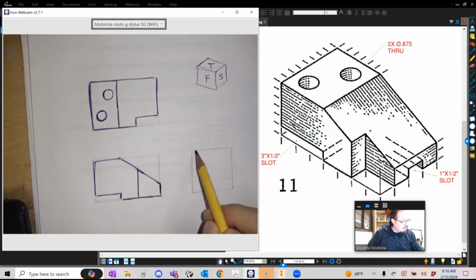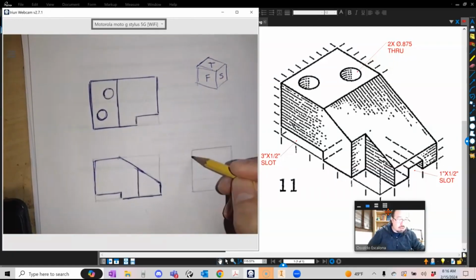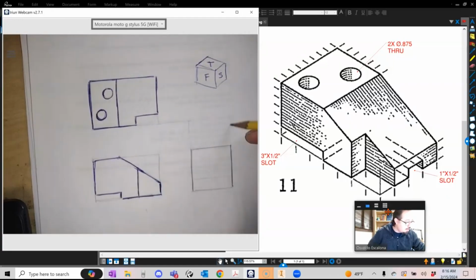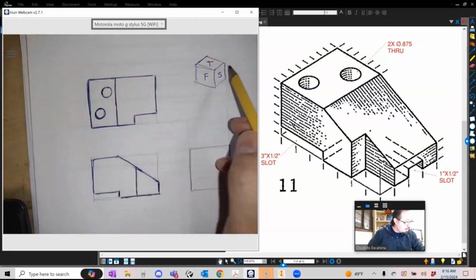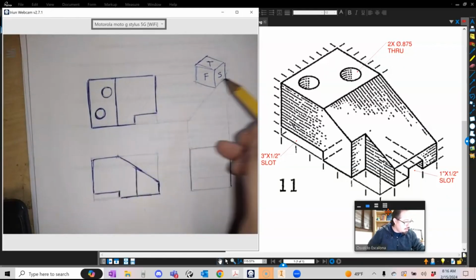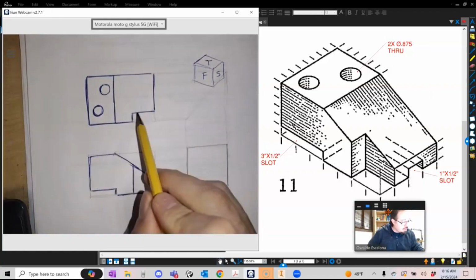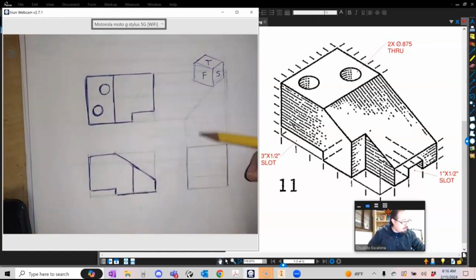So if I were to look at the side view, it seems to me it's going to go across the whole part, something like that. And then it seems to me here, I can make a little 45-degree line here. Because if you do a 45-degree line, you can actually get the right depth. So this line here, I want to project right there on the 45, and then I want to project it down. And then this point is this point, right?